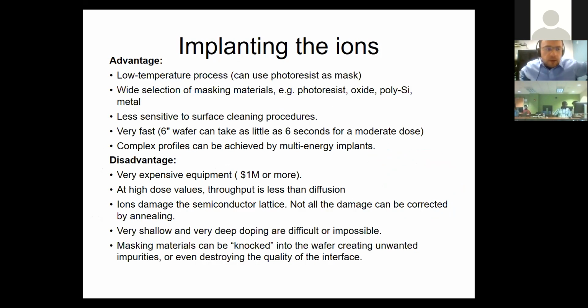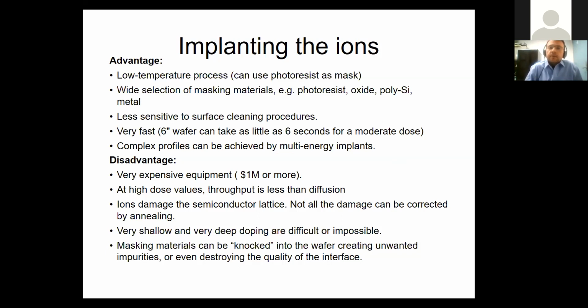Increasing the temperature, you should always keep in mind that there will be thermal expansion going on all the time between your layers. So there should be more and more stress build up. If you have several cascaded layers, increasing temperature can be critical. Also keep in mind that you might have polymers in your case, like you will see next week, like photoresist. They will be very susceptible to temperature deviations, and they can't really survive after 200 Celsius or so. So all those are going to be critical.